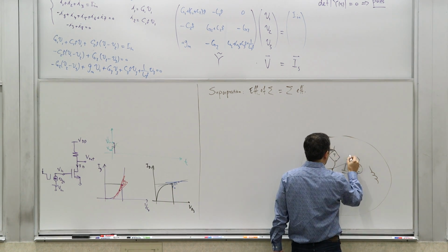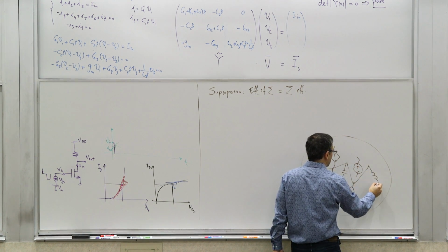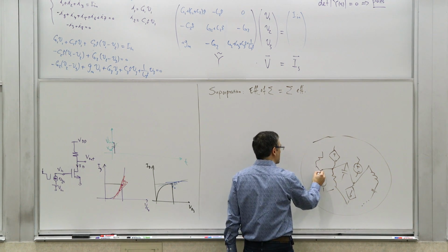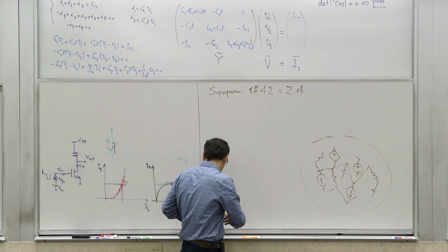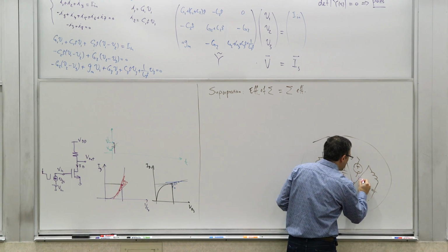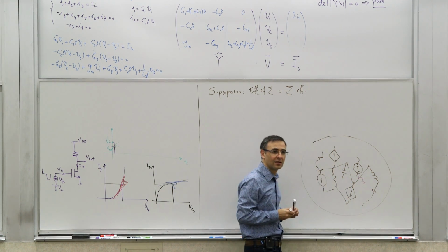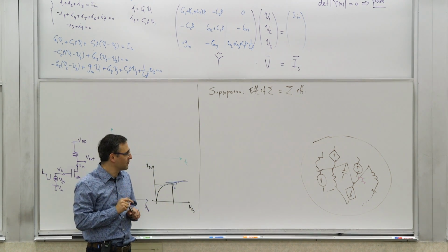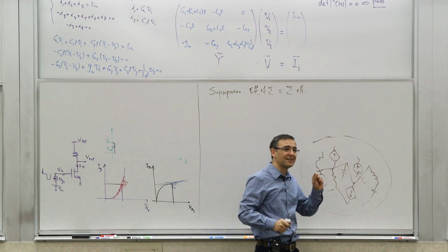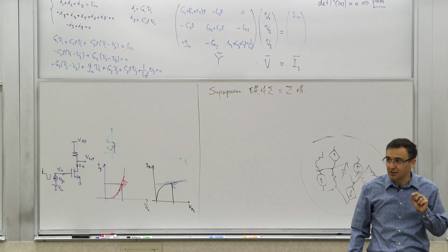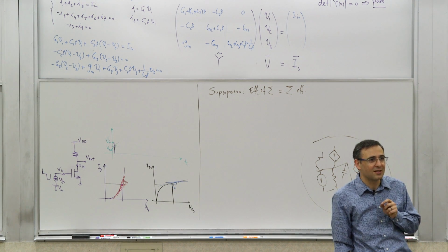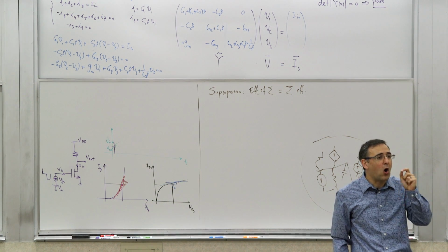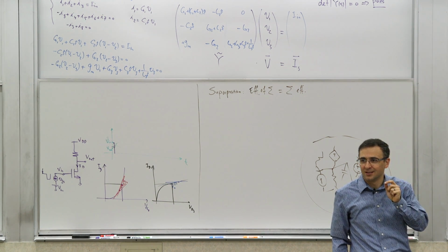And we are interested in certain behavior of certain parts of the circuit, say certain voltages or currents. What it says is that if I am, for example, interested in this current, Ix, I can calculate Ix by setting all, and this is the key part, I'd like to emphasize this because it can lead to a lot of problems if not paid attention to, you null with 0 all independent sources.